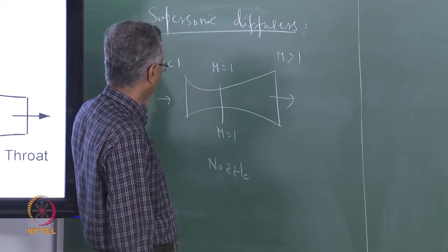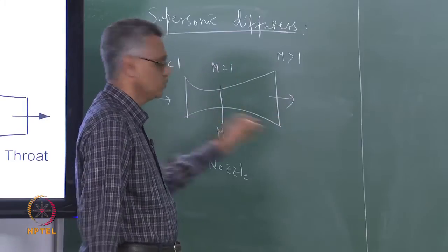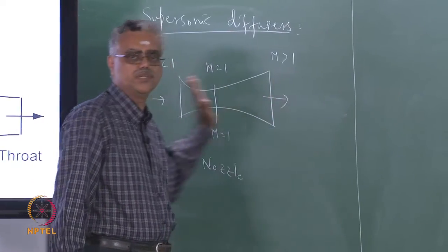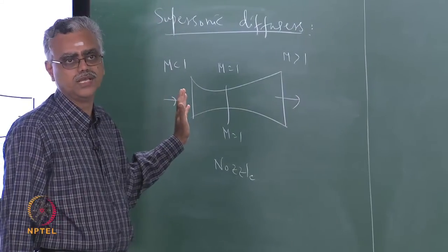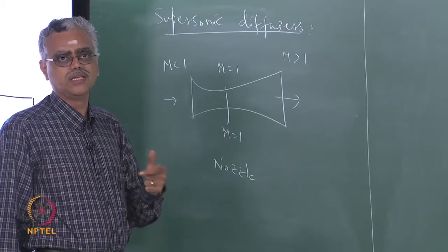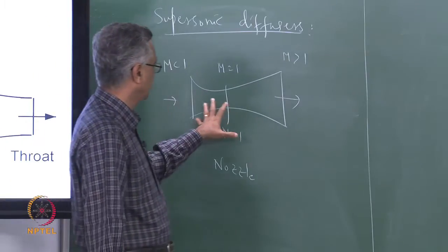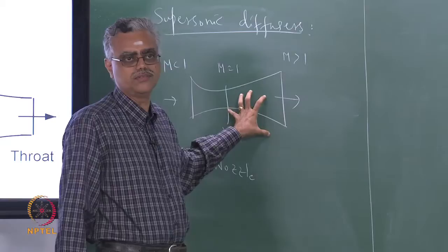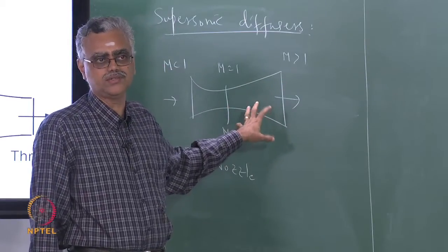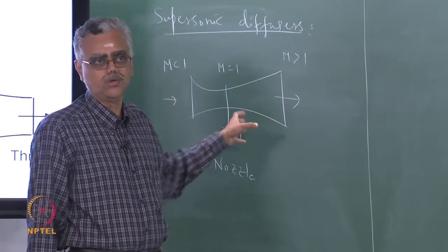And if you remember, the pressure decreases from here to here in the nozzle operation. So similarly in the diffuser operation, the static pressure would increase from here to here. That is the general idea. But because you have a normal shock during startup of these devices, you have a lot of difficulty realizing this in practice. This sounds very good on paper, but is very difficult to realize in practice, and those are some of the things that we are going to look at now.